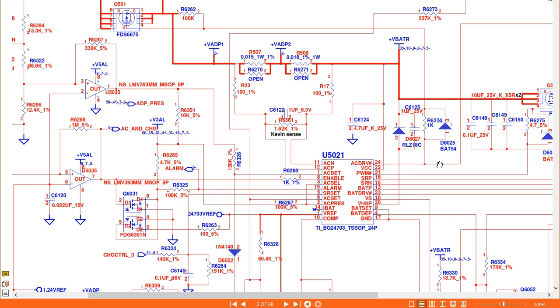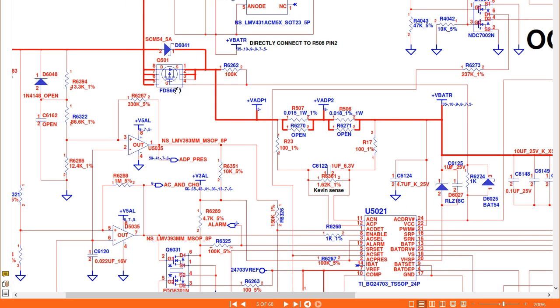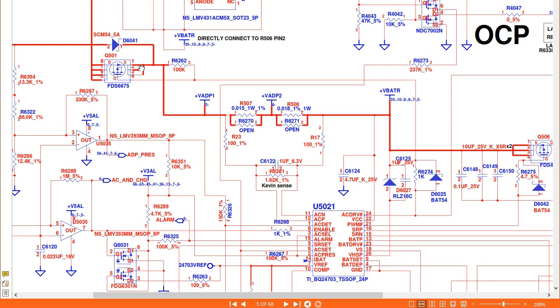The AC drive, as you can see, this is the control signals. Okay, so after receiving the control signals, 19 volt will pass here to the source. Here we have the drain, 4 pins connected together. Here we have the source. So we're gonna get the 19 volt here.